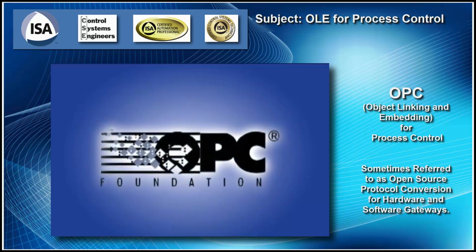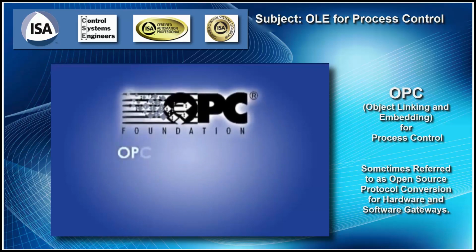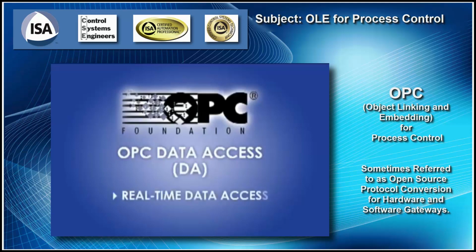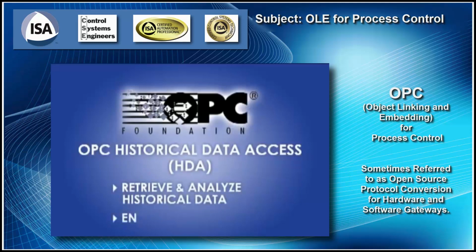Some of the core standardized specifications OPC Foundation members came up with include OPC Data Access Specifications, which provide real-time data access, a timestamp, and a quality code for each value requested. OPC Historical Data Access, HDA, which can be used to retrieve and analyze historical data and enable analysis, trending, and reporting. The HDA typically retrieves data from a historian or relational database.